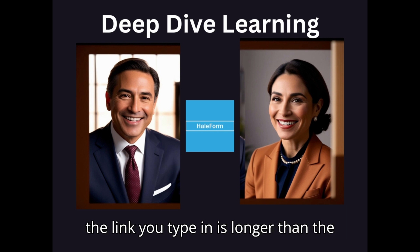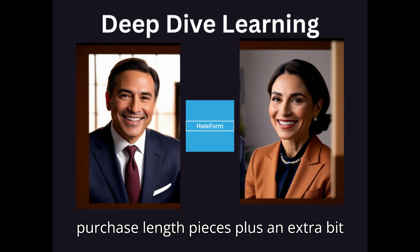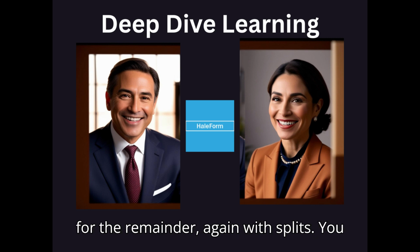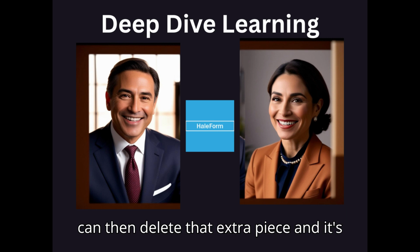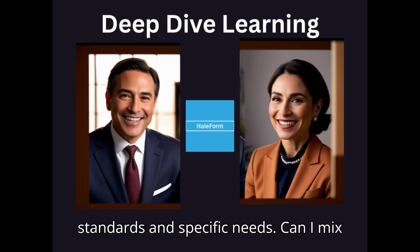Now, if the length you type in is longer than the standard purchase length, Smart 3D places purchase length pieces plus an extra bit for the remainder, again with splits. You can then delete that extra piece and its split if you don't need it. Gives you flexibility. Good balance between standards and specific needs.